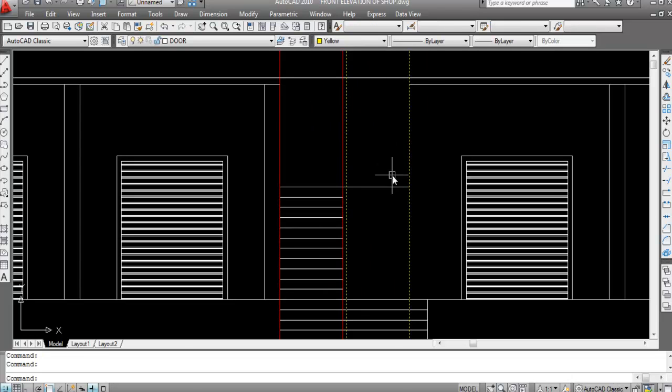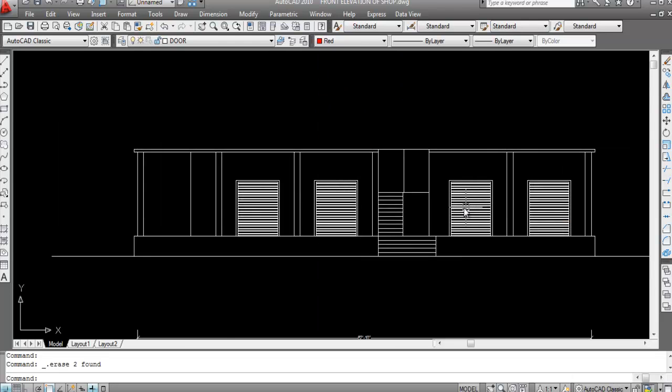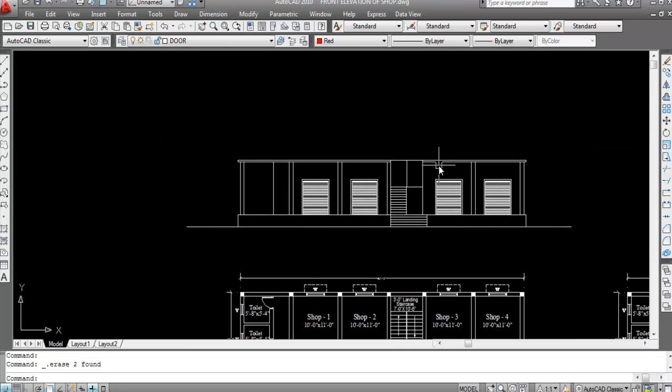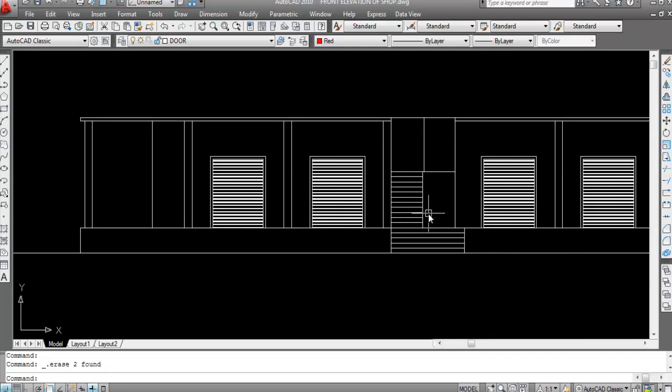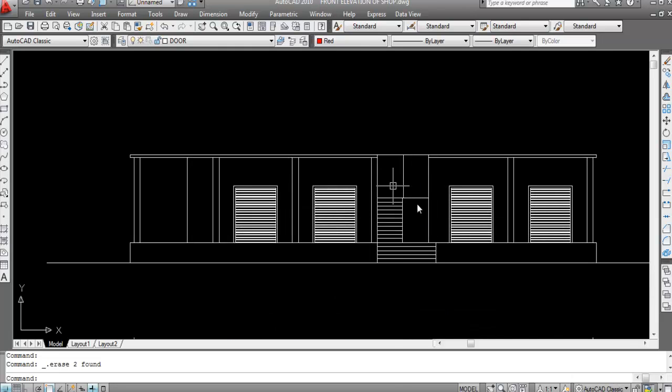Okay, here to here we can see only the slope here. We can see the steps from backside slope. We can't see the risers here. Alright, so hope you understand. This is the staircase. So the staircase is created. So always remember, on front elevation we can see the risers and on top view we can see the treads. Okay, risers is 6 inch, treads are 9 inch.